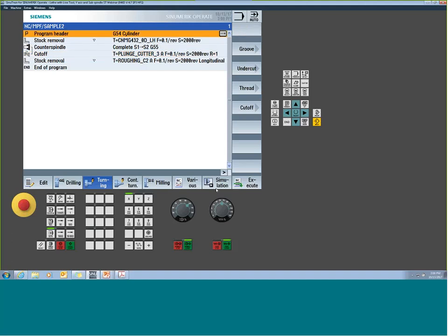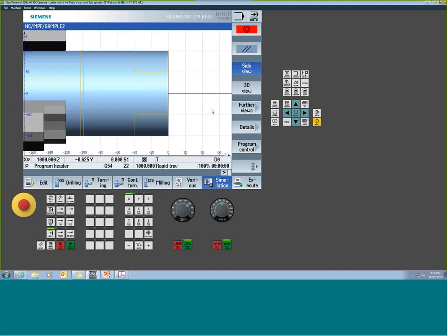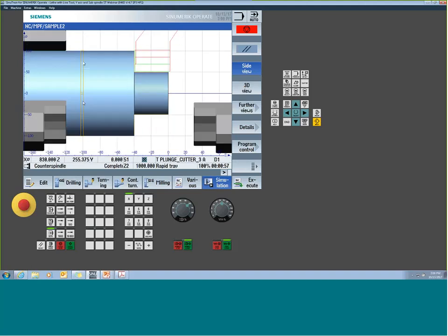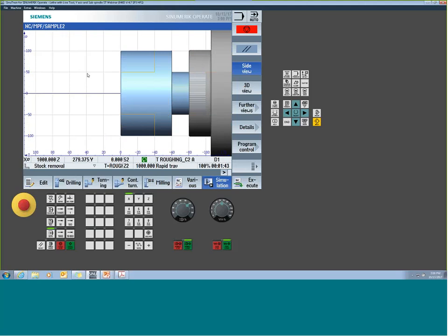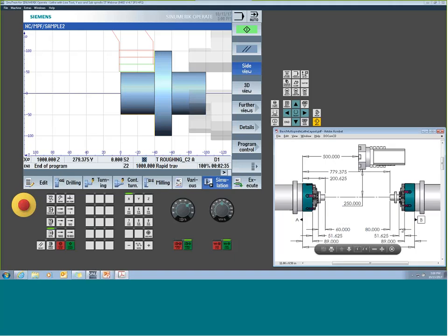So now, if we start to look at it, we see the part off cycle. The whole thing's sticking out further. There's my part off. Then she moves back. We get our secondary operation. And while everything stacks, everything makes sense for us. So it's really quite simple once we get to the part off, as you start to see. The big trick is just getting that initial setup, making sure you know where everything lies dimensionally. Then all the numbers make sense. If not, you're just chasing your tail.